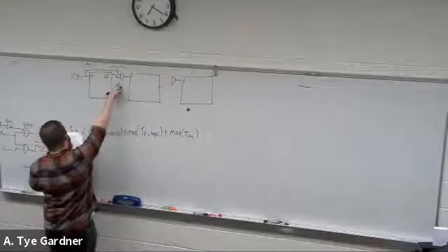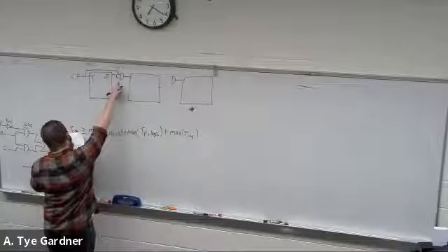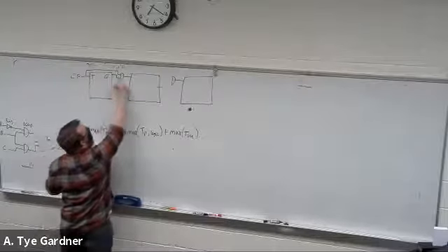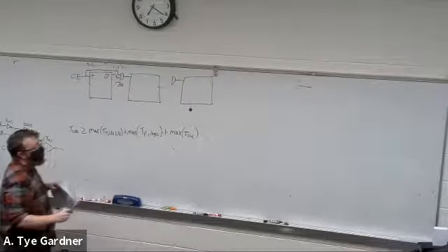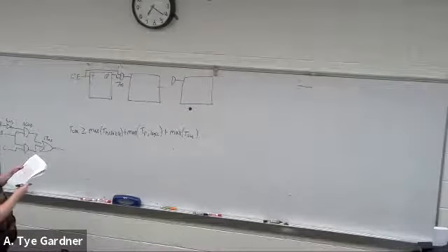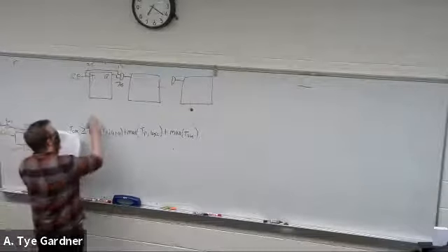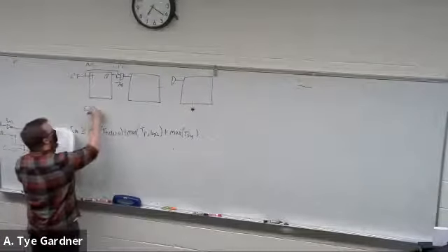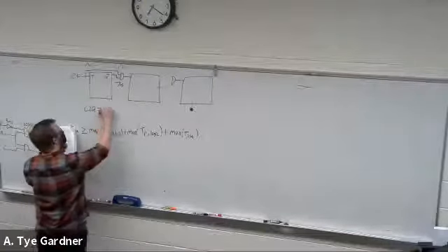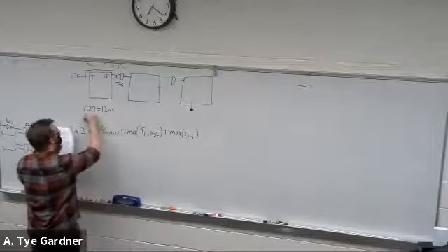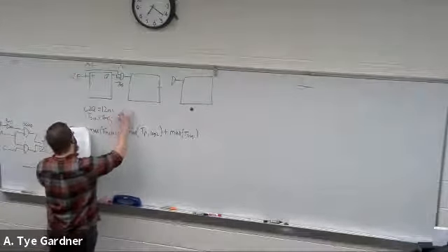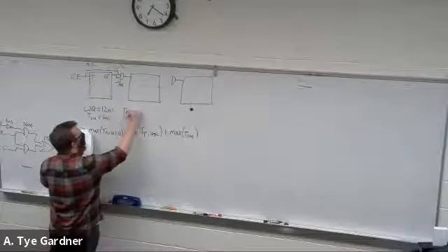Whereas here, we want our logic delay of the AND gate to be 7 nanoseconds. And then we want the flip-flop to have clock to Q set at 12 nanoseconds, TSU equal to 6 nanoseconds, and a T hold of nothing.